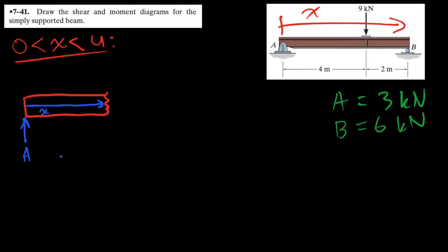Now, let's draw our beam convention at the right end of our sectioning, because that's where we section, so that's where we want to write our beam convention. The beam convention starts with a shear force here, denoted by, let's say, V1, and we have a moment like this. Let's call this M1, and we have a normal force, N1. Clearly, in this system, there are no horizontal forces, so N1 in this case is not relevant.